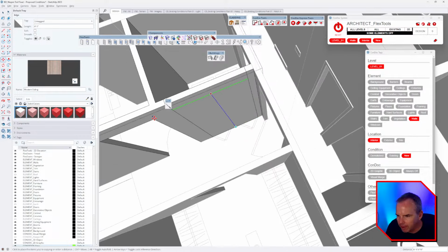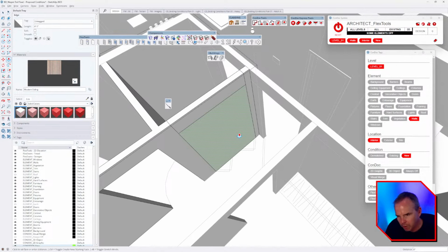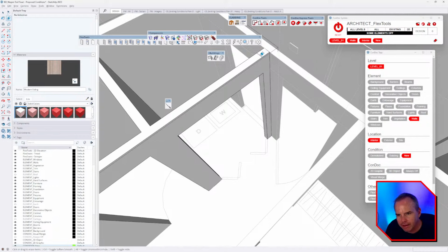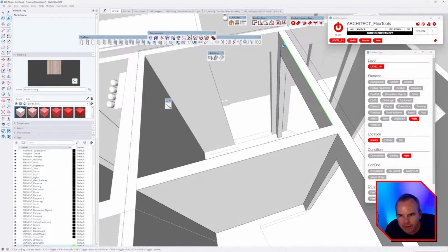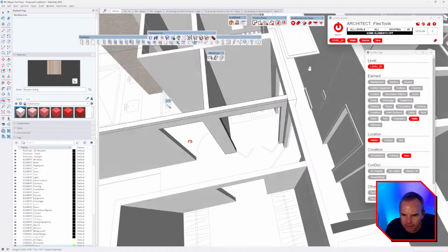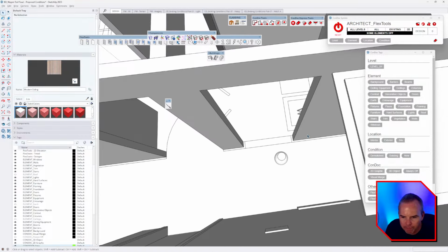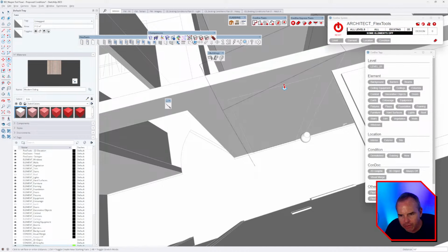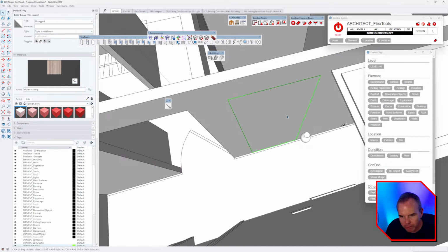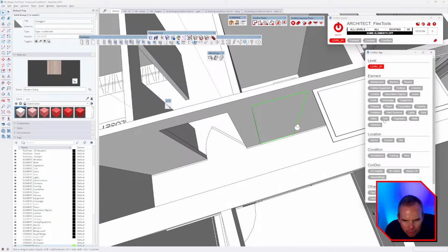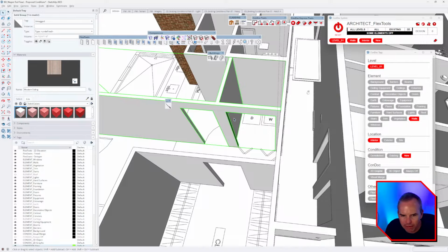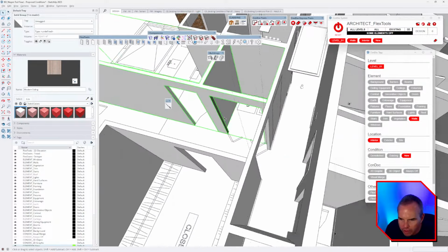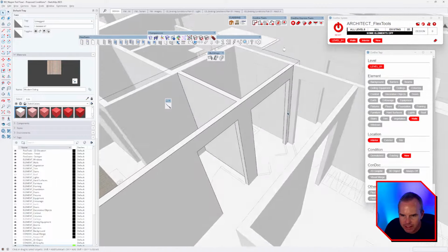All right, tap the up arrow key to lock that blue, and then I'll push-pull like that and clean those up. All right, and then as far as a new wall goes, from here to here is a new wall, and then I need to pull that down like that, and again I'll explode it, group it, and this is going to be level 1 walls interior new, and then this is level 1 walls interior new. This I want to reverse my face like that,